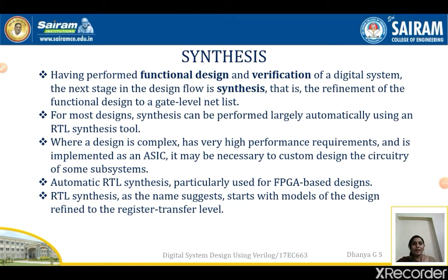Having performed functional design and verification of a digital system, the next stage in the design flow is synthesis. That is the refinement of the functional design to a gate level netlist. For most designs, synthesis can be performed largely automatically using an RTL synthesis tool. Where a design is complex, has very high performance requirements and is implemented as an ASIC, it may be necessary to custom design the circuitry of some subsystems. Automatic RTL synthesis is particularly used for FPGA based designs.